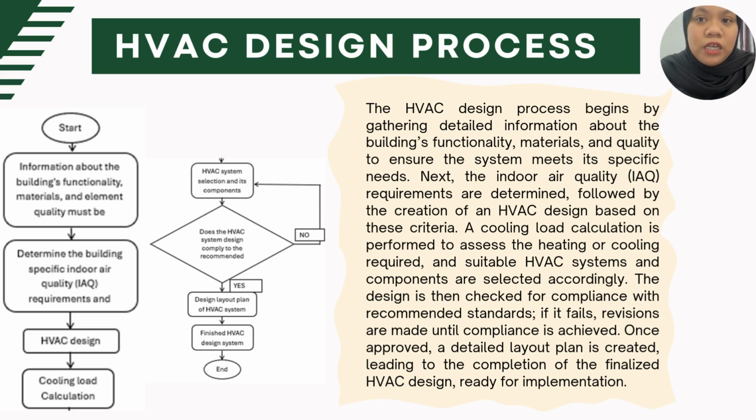Next, the indoor air quality requirements are determined, followed by the creation of the HVAC design based on these criteria. A cooling load calculation is performed to assess the heating or cooling required, and a suitable HVAC system and components are selected accordingly.